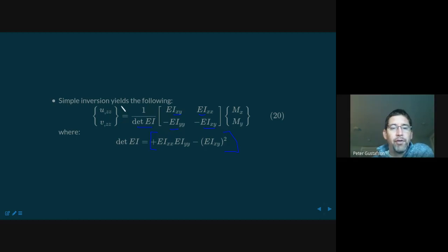But as we stare at this equation, what do we see? Well, we have on the left-hand side an expression for the displacement. Now, it is the second derivative of that displacement, but it is the beginnings of an expression for the displacement. This is the amount of deflection that beam undergoes as it's bending. What do we have on the right-hand side? Well, we have something that relates to the geometry, that is E and I, and the material. So E represents the material, I represents the geometry, and then, of course, the right-hand side vector, mx and my, is the load. So this column here is load.